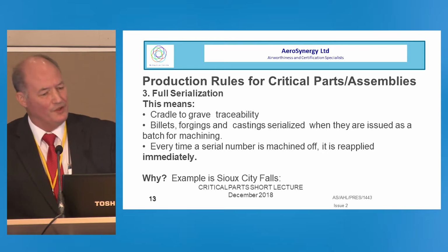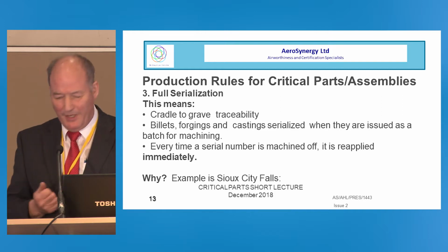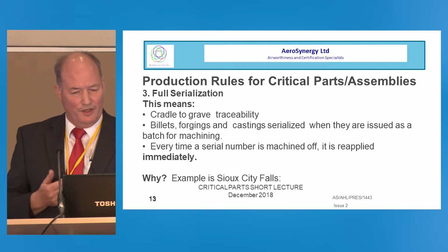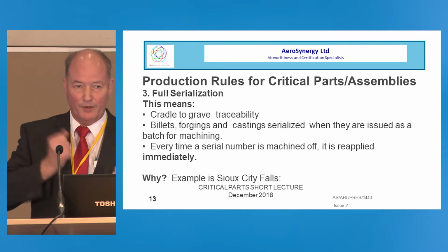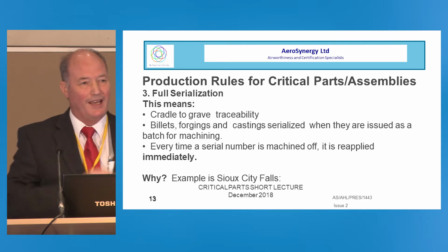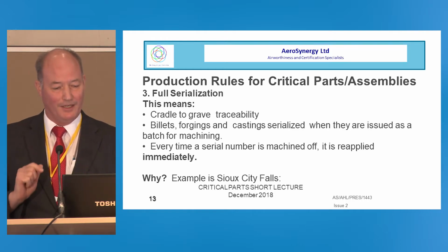Full serialization, what does that mean? It means cradle-to-grave traceability. Billets, forgings, and castings, they're all serialized when they're made. And when a billet is issued, the serial number goes on right at the beginning. Every time the serial number is erased by machining, it's put back immediately.